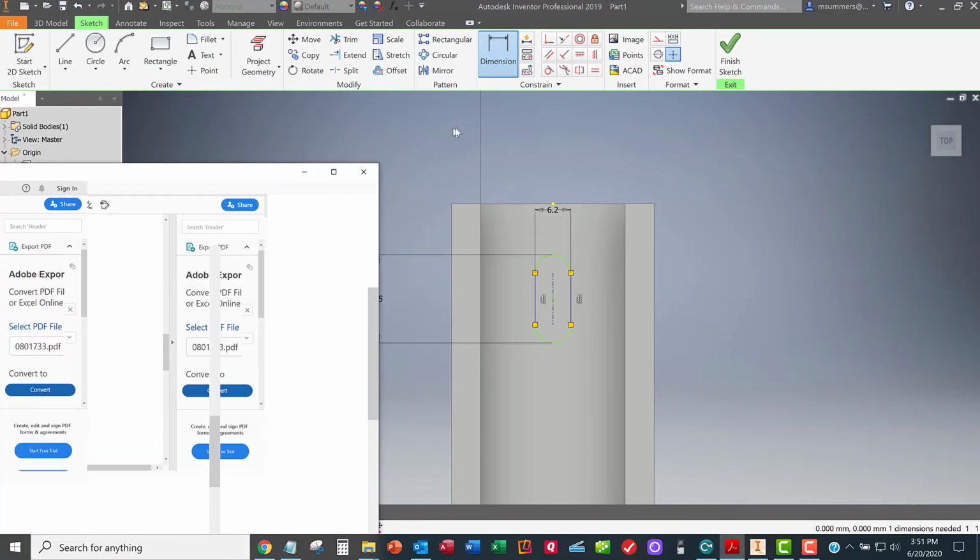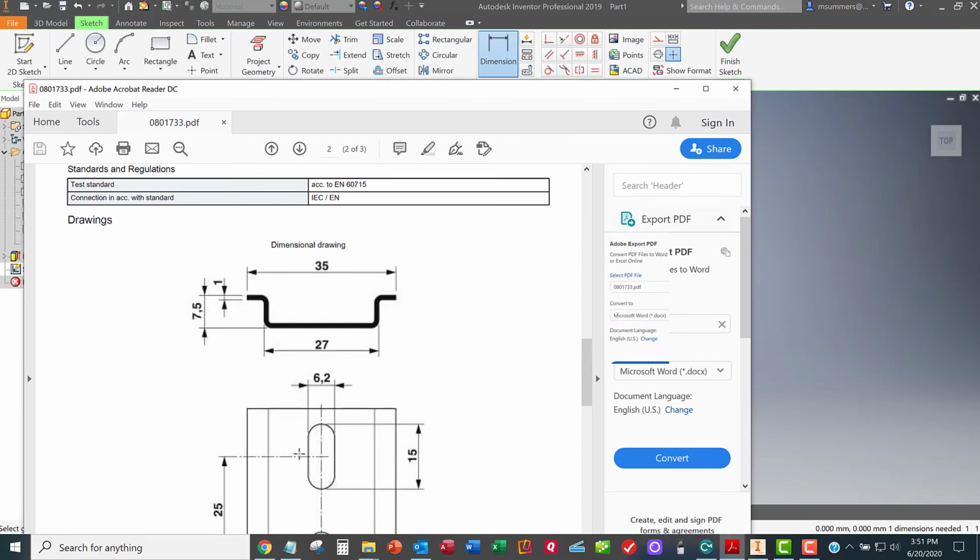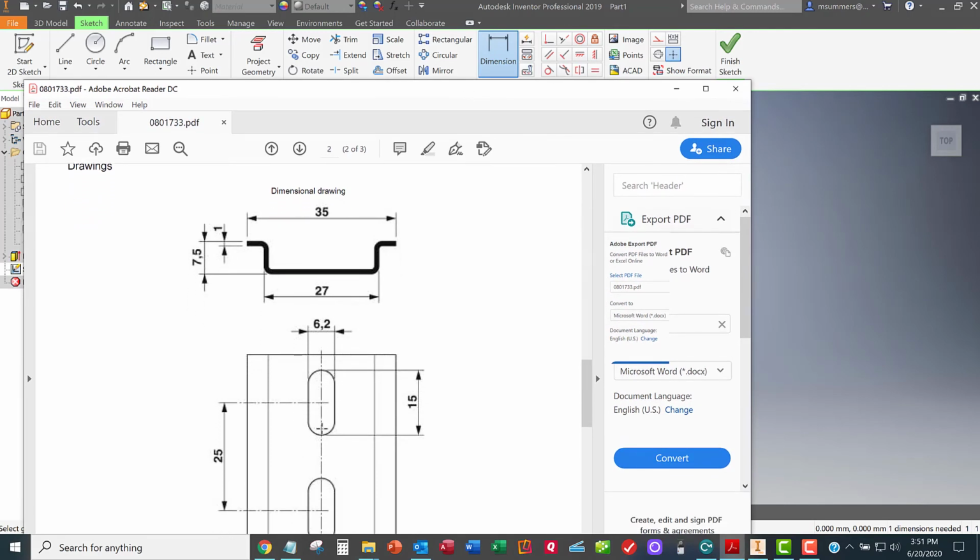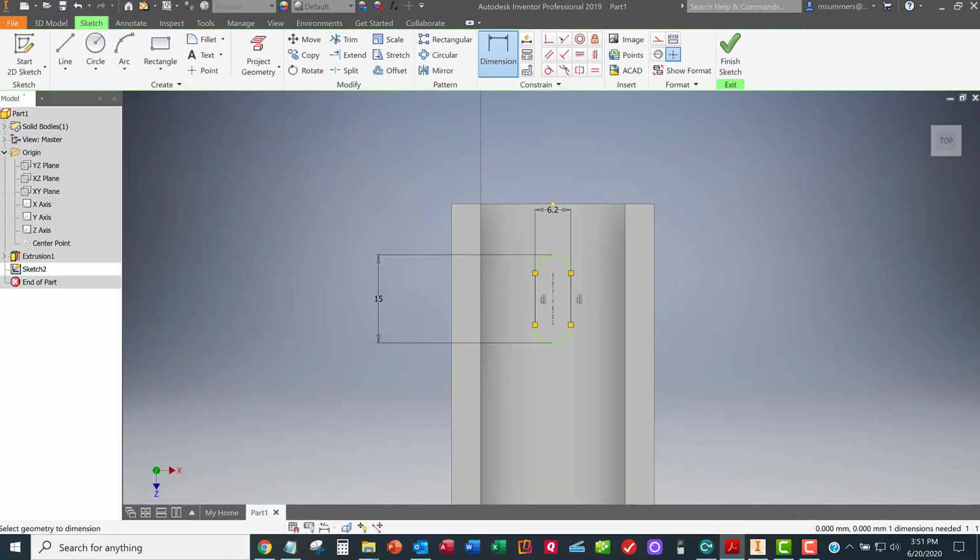halfway between the slots. And so if it's 25 millimeters between the slots, if I cut it right in the middle between 2 slots always, then this edge here is half of 25 from the edge. And so let's do that. Now I'm glad I've got that point here. I can dimension between that point and this edge and I can just type in 25 divided by 2 and Inventor will do that calculation for me. It says fully constrained, which is what I'm always looking for.